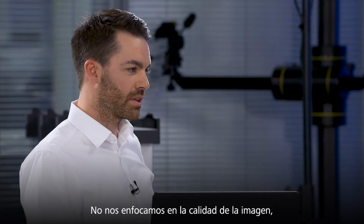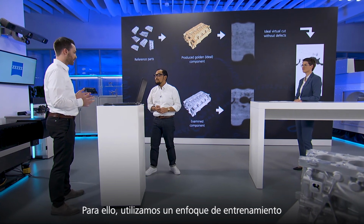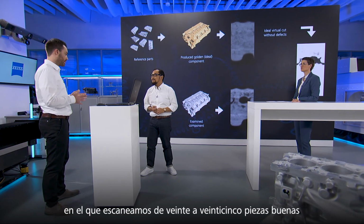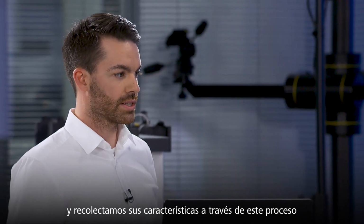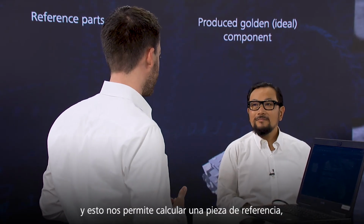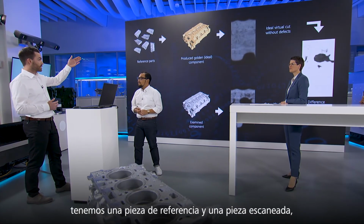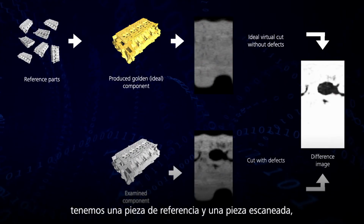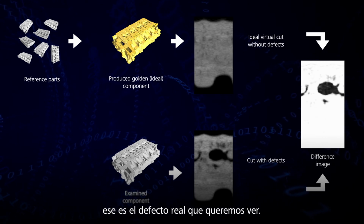We are not focused on image quality, we are focused on performance. For this, we use a training approach where we scan 20 to 25 good parts and collect features during this process. This allows us to calculate a reference part, or so-called golden part. At the end, what you can see here, we have a reference part and a scan part, and we see the deviation, and this is the real defect which we want to see.